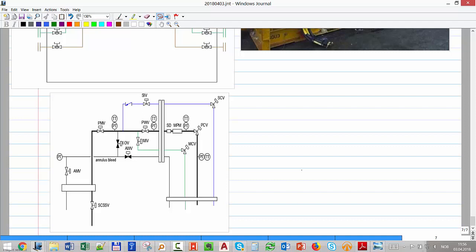So during the injection of these inhibitors, the gas stream is closed, like the production stream? No, it has to be continuous, otherwise you get hydrates. So that's why you see here, for example, maybe methanol, they don't need it all the time. They just need it on demand basis. And here you have a choke to control the rate. Remember that you have a single conduit that comes at a very high pressure. So the only way to control the rate is if you have a control choke in each well, so you can control how much you're producing. But here you have a check valve, for example, on the scale, such that you don't get backflow.